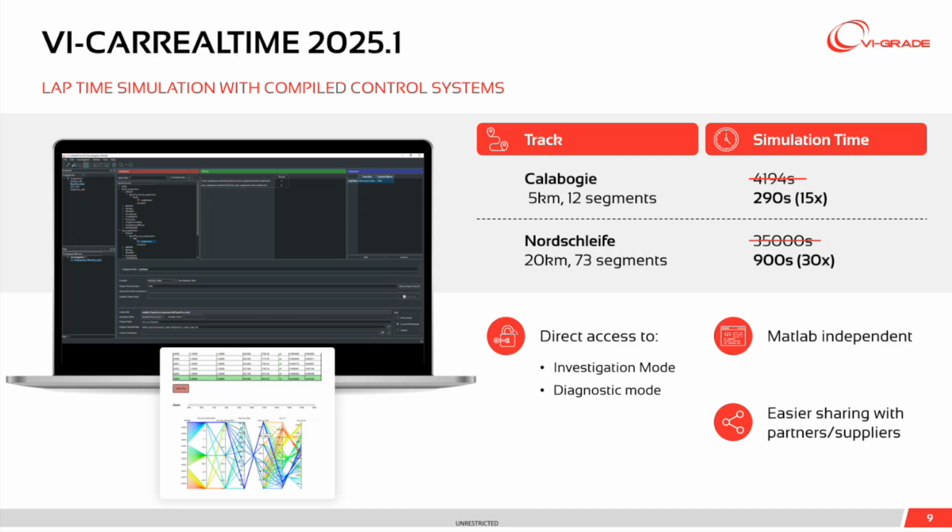In addition, this is not the only advantage of running with the Simulink model exported and integrated in VI-CarRealTime as a plugin. This integration gives also full access to all VI-CarRealTime features, including diagnostic mode, and also allows to perform investigation mode much more efficiently than when used in co-simulation. Not to forget that by exporting the model as a plugin, we automatically protect our intellectual property in case we need to share the component with customers or suppliers.